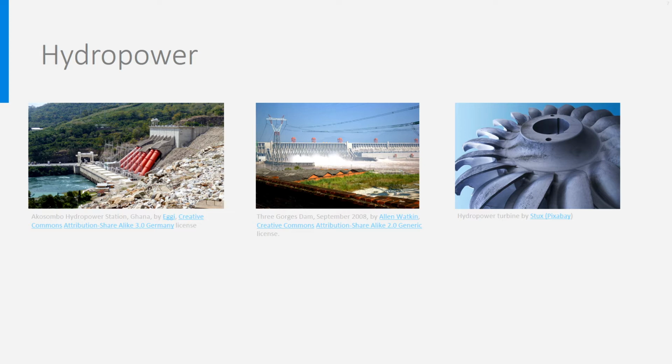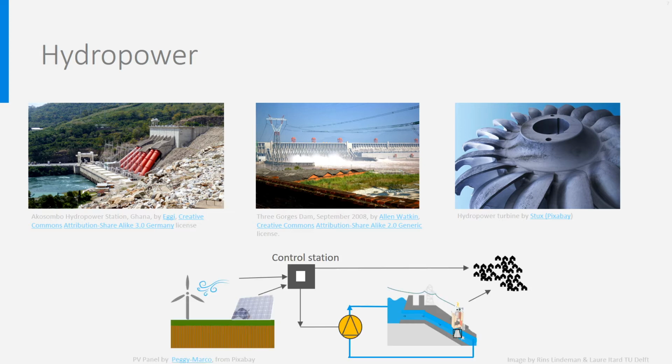Finally, hydropower can also be used as storage for excess electricity generated by the sun, photovoltaic panels, or by wind. When their production is very high and exceeds the demand, the electricity can be used to pump water into a reservoir. This reservoir will produce electricity later by hydropower. This allows for a good integration of diverse forms of intermittent renewable energy.